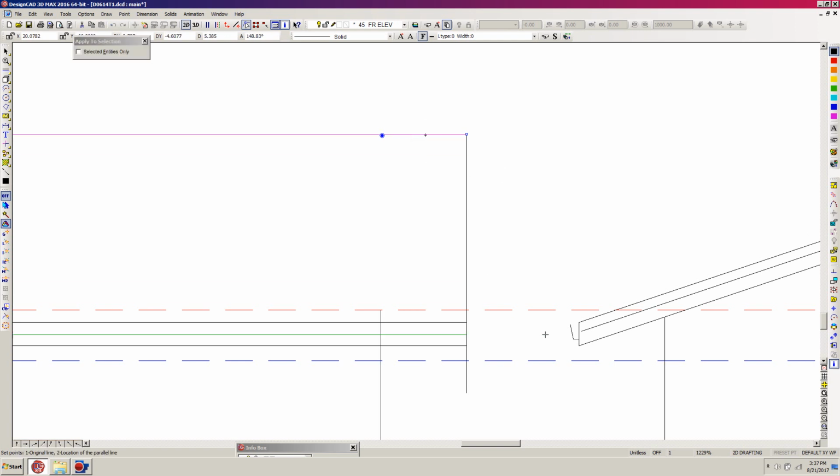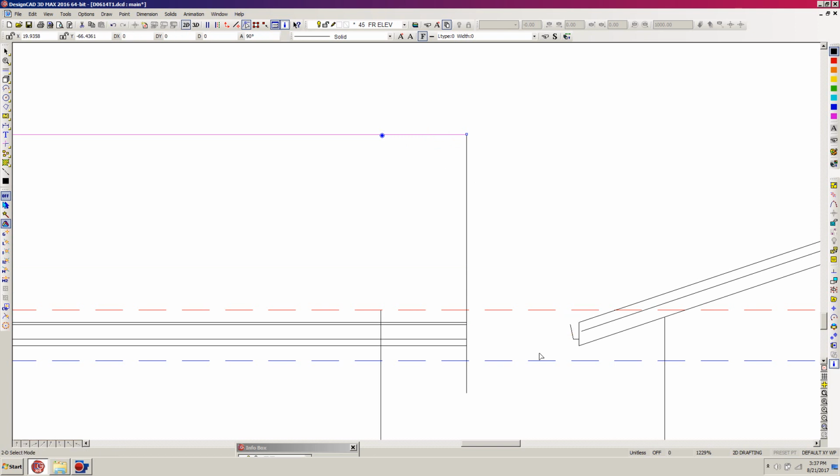for parallel, come up and draw at the bottom of my gutter. And I think the top of the gutter and the top of the fascia are really pretty close to each other, but we can go ahead and draw a top of gutter also. And actually we're going to need to seal this gutter at the end, because that's still from our section drawing. So I'm going to hit equals for parallel and just come on down to the top of the gutter and see how that looks, and there it is.